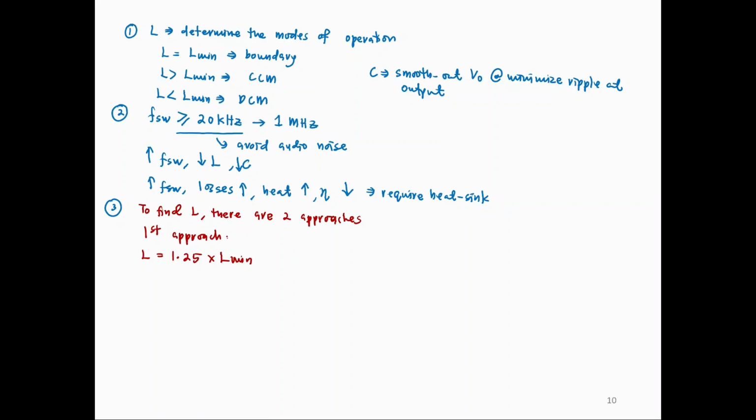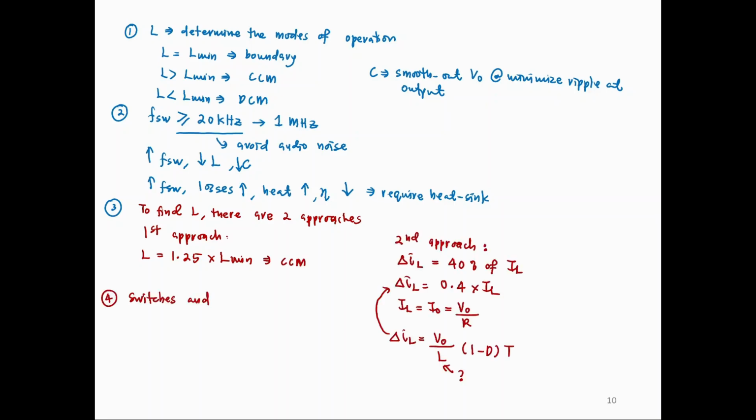Okay. In terms of switch, you can select any switch or diode, but make sure it is able to withstand maximum reverse voltage and current.